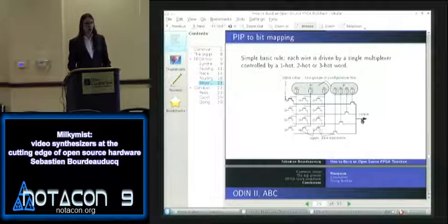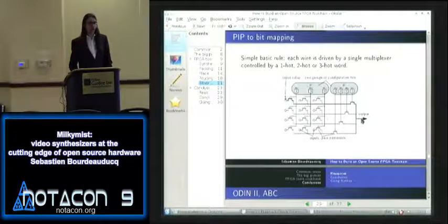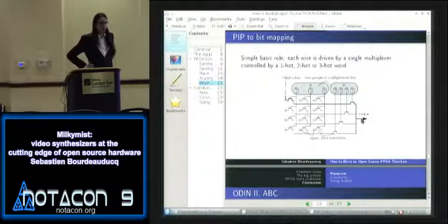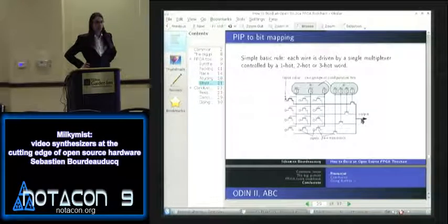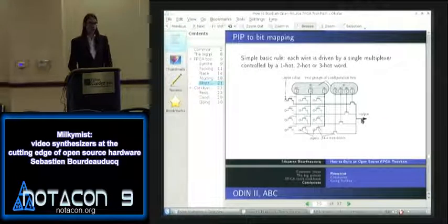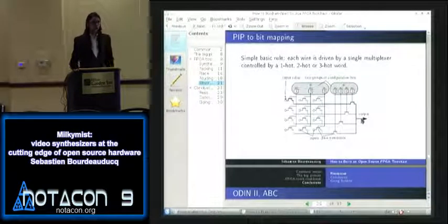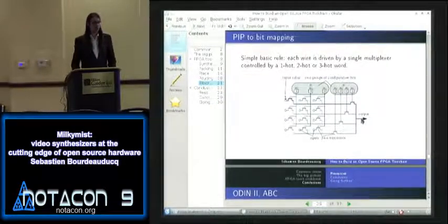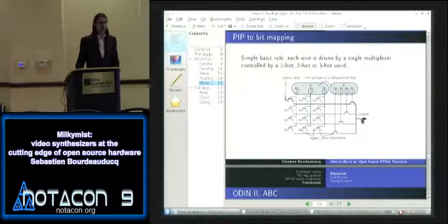Right now, we are able to run the user interface at 1024 times 768. It doesn't work in rendering mode yet because of memory bandwidth problems that I'm going to address in the next version of the system on chip. It works as well without the transceivers. This Spartan 6 chip we are using today is capable of doing HDMI and DVI, and in the very next version, which is actually being manufactured now, it's being routed at the moment, we are going to replace VGA with DVI, and you will have DVI-D. So it is possible to do it with minor changes to the current design. You don't need a higher end chip. No, they are not more expensive anyway.